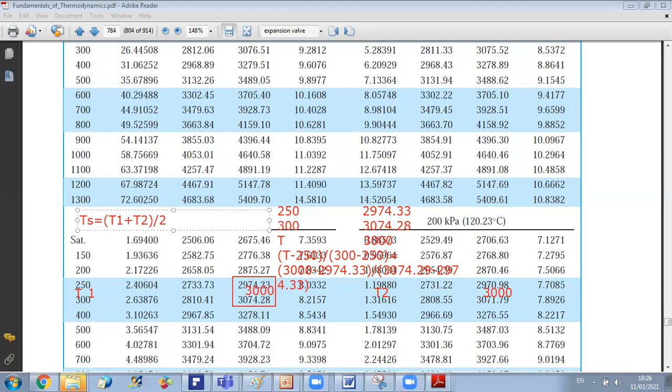Okay. So doctor, I use the H out in order to get the temperature? Yes. So here H out will give you the saturated temperature, exactly, using interpolation. But here since H out luckily was in the saturated zone, it's much easier then.